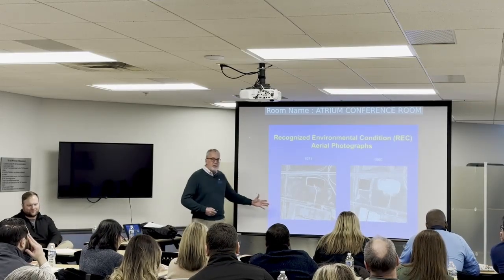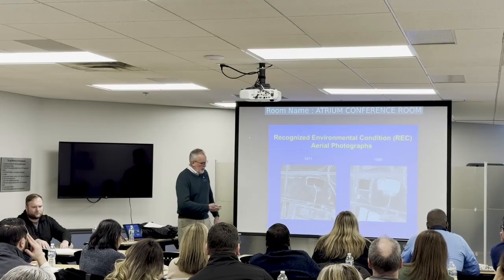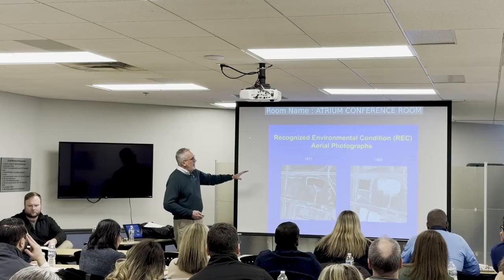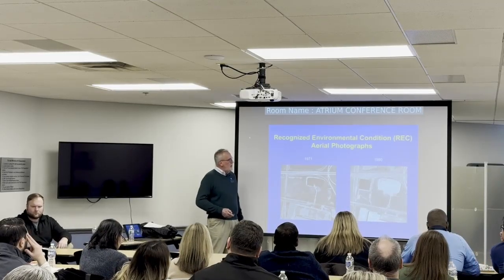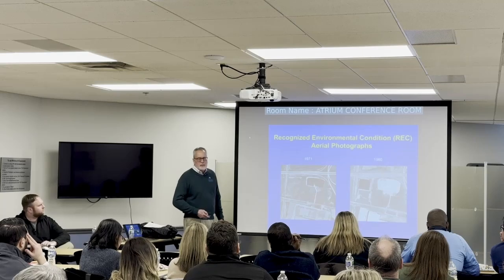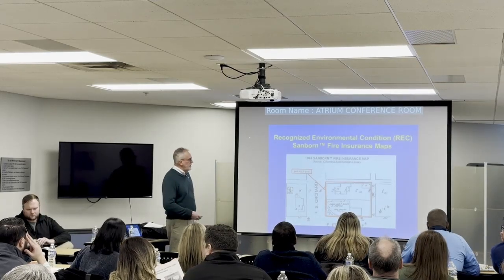Historical topographic maps, same thing. If you've got a site that's got a big valley and then that valley disappears, what's going on? Back in the day, 70 to 80, solid waste rules were getting rolling, but anything prior to that, they just looked for a place you could bury stuff, mining sites, those kind of things.